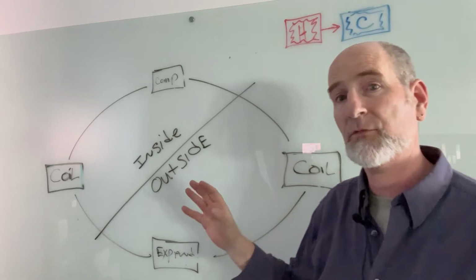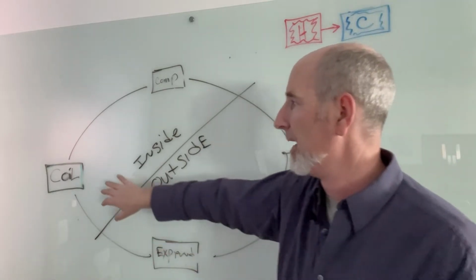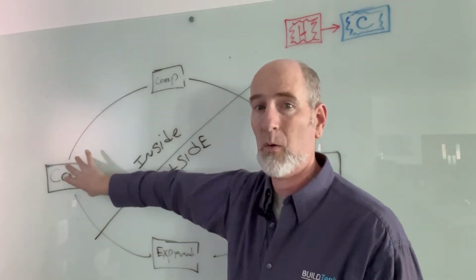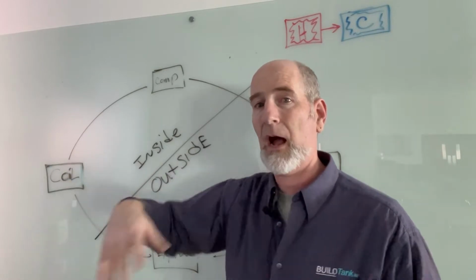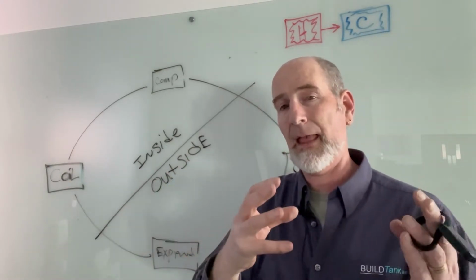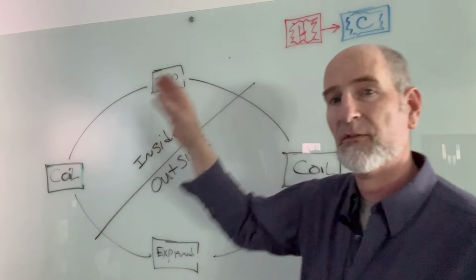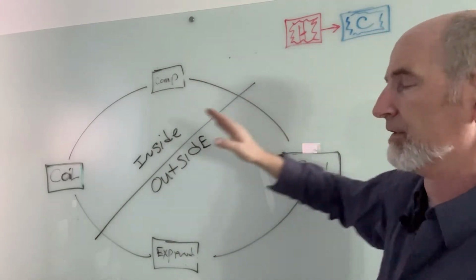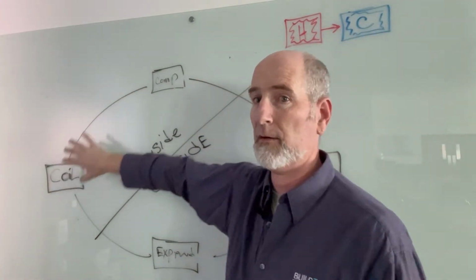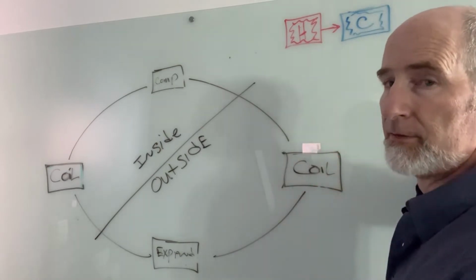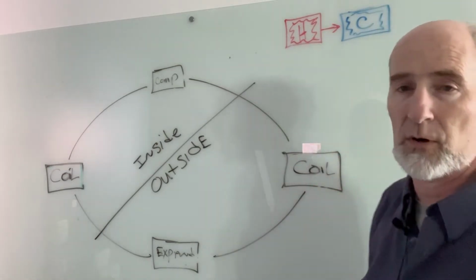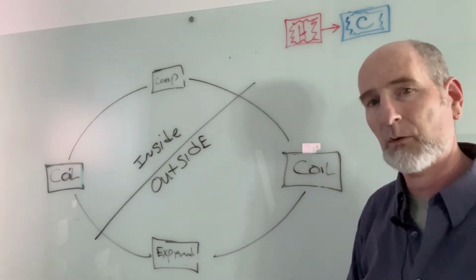And so if I'm trying to cool a house, I need to make this indoor coil cold in order for the hot air inside my house, and the energy in that hot air, to move from higher concentrations to lower concentrations, from the air into the coil and then ultimately to the outside. And that's what cools my house.